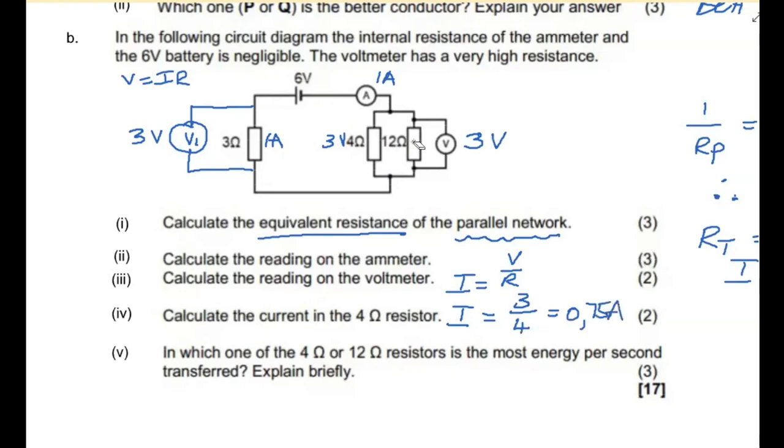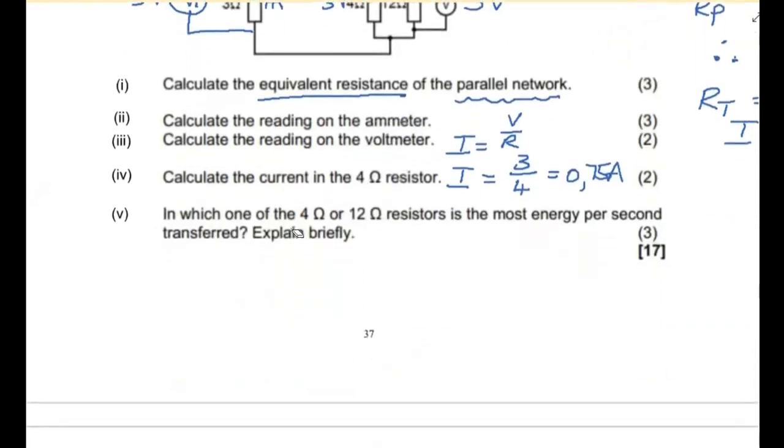Storm, be careful, you've done the 12 ohm. Yeah, because remember the 12 ohm will have the smaller current, so if you've worked out the 12 ohm, then subtract that from 1, and then you will get to the answer. Storm, did you use ratios there? No, ma'am, I calculated the 12 ohm. Okay, no, just checking. Because sometimes kids use ratios and they don't realize that when we're talking about current, remember the bigger current must go through the smaller resistor. So you've always got to swap. If you found it for the one, you must make sure you swap the ratios with current.